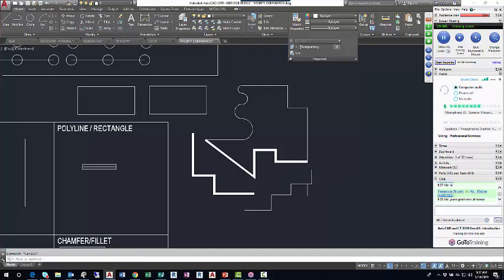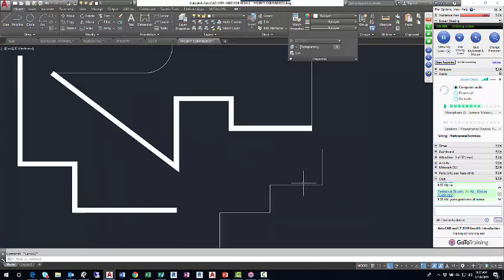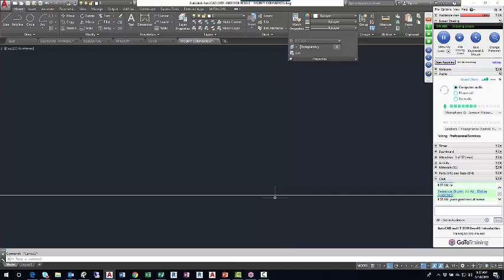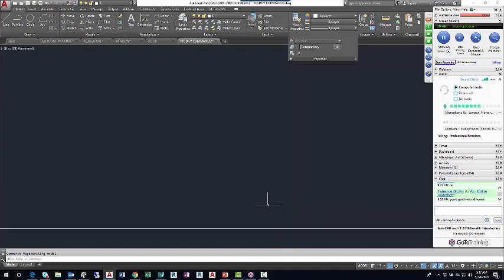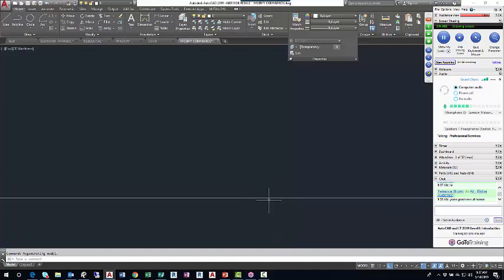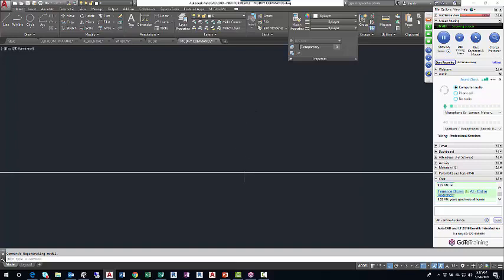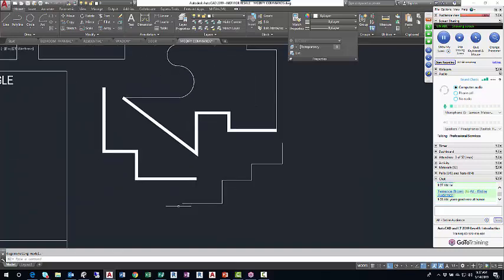The idea behind that 0 width, which sounds nonsensical, like if it's 0 inches wide, how can I see it? Well, 0 allows you to zoom up on this all day long, and it will never change its thickness in your viewport on your drawing window. So someone who draws football stadiums can use the same tool, Polyline, as someone who draws microchips.